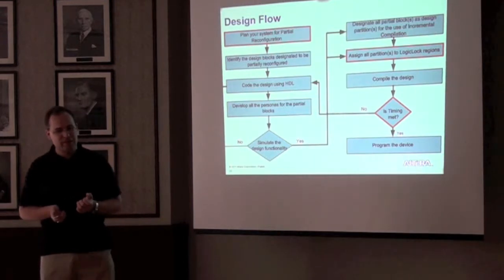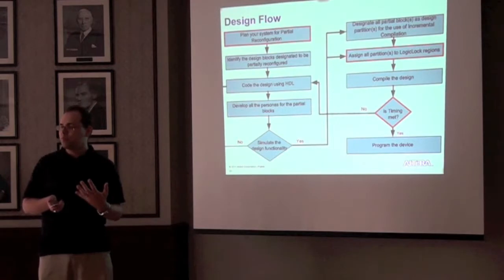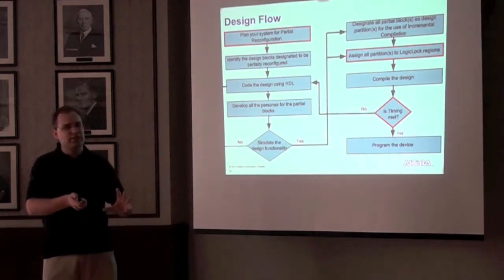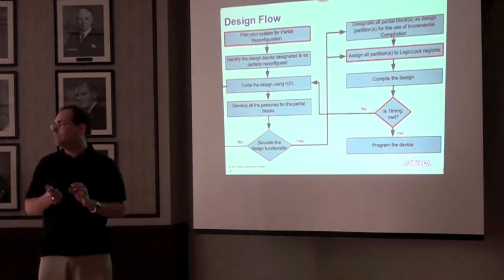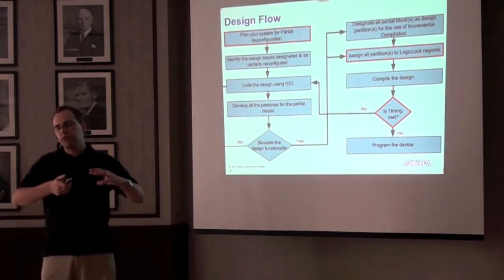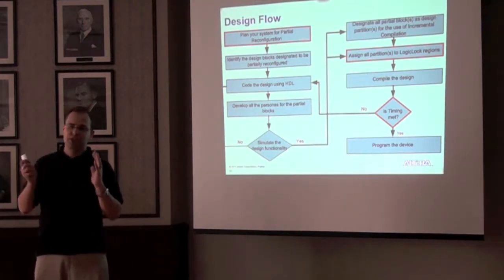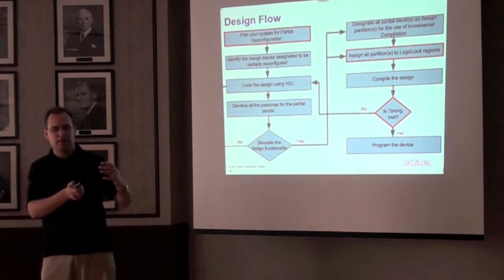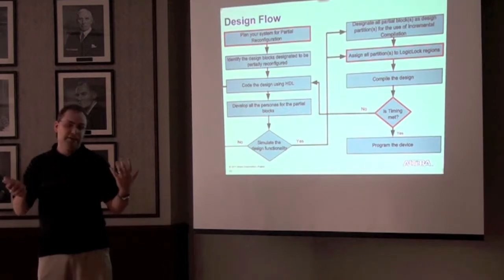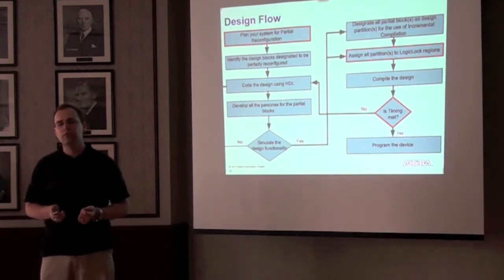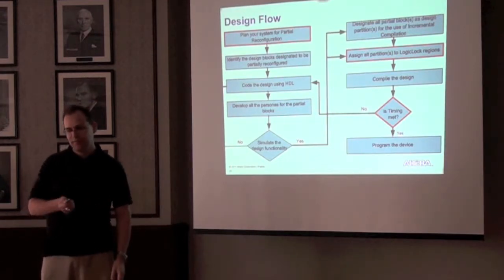That's a problem for anyone going down this road, which is why it's important to be modular and make sure that each persona is able to meet timing independently, such that when you do the entire system, you don't come up with a situation where I have to change what my data path looks like in the base revision, because that will trigger a recompilation of everything, and realistically, that design cycle will be more expensive than just doing one compile at a time.